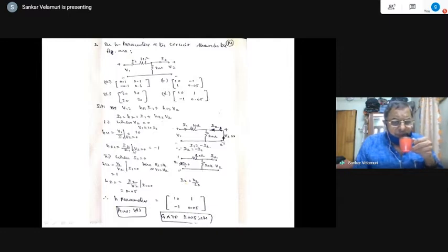Both are different, but in magnitude they are the same, but this is the ratio of the currents, so it is minus of that. So H21 equal to I2 by I1 when V2 is 0 is -1. H12 is V1 by V2 when I1 is 0. That means when port 1 is open circuited, the ratio of the voltages will be the same in magnitude as the current ratio with V2 equal to 0, as in a reciprocal network. See how typical it is.